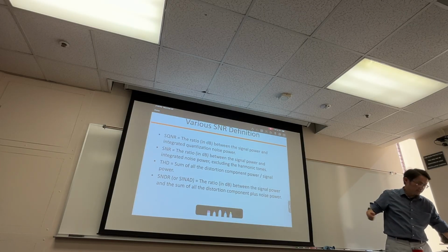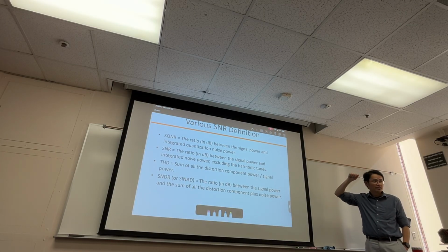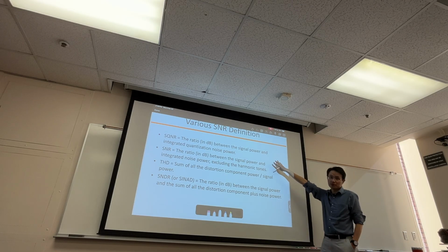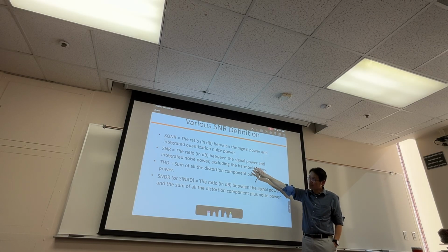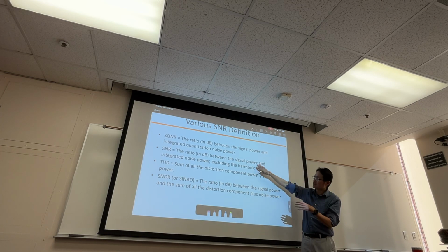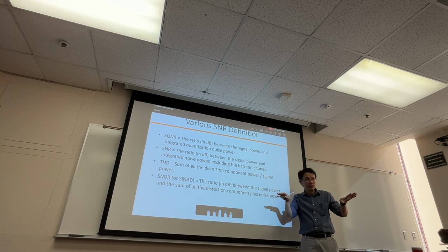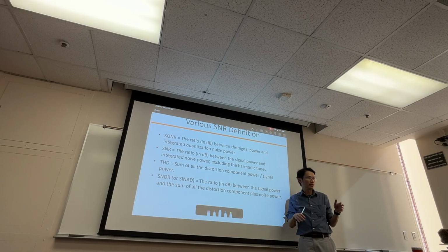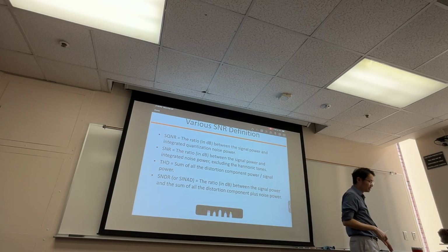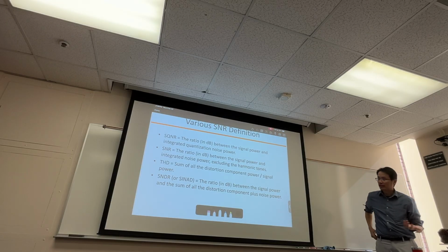So here's a question: can SNR be higher than SQNR? No way. By the way, this is a sanity check. You design your ADC, you know what your SQNR is. If you simulate and compute, I do exactly like this, I compute the signal power divided by the noise power. If that ever becomes higher than your SQNR, you better go back and check. Something must be wrong. Most likely your test bench is wrong. That's why you get an even higher number than your SQNR.